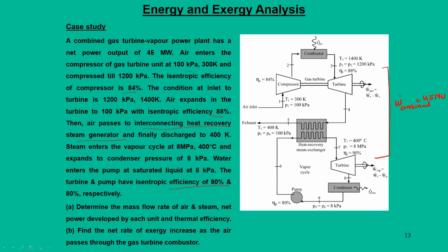So, what we need to find out is, our main objective is that with the basic data points, we have to individually calculate the steam cycle unit and gas cycle unit, which has been emphasized in our previous lectures. Normally when you say steam cycles or vapor cycles, we look into the modified Rankine cycle, and the necessary steam data we can obtain from the steam tables, and based on that we can find out the enthalpies at various locations for the vapor cycle unit.